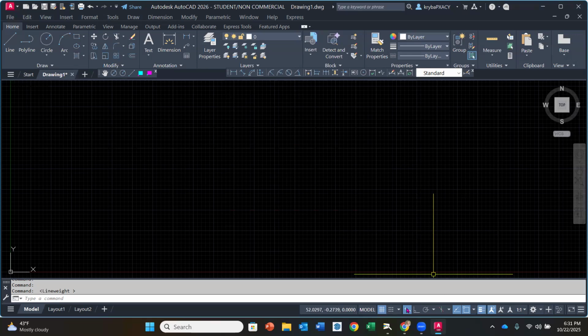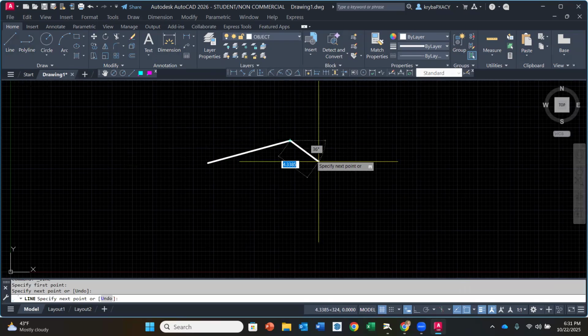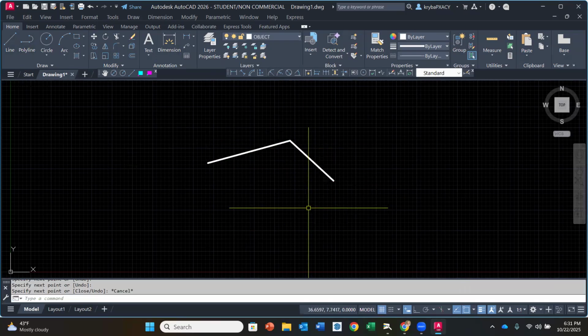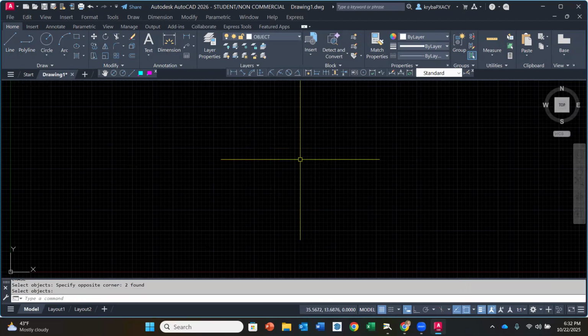So you've got to look down here. Mine is right about there, where the line weight I just added is. Okay. Now, why is this nice? I'll show you. When I put this on the object line layer and I draw a line, my line is a lot thicker and I can see it better. I like using it for demonstrating purposes, but I know students like it too because they can see their object lines better and more defined than other things. All right. So I'm going to get rid of that.